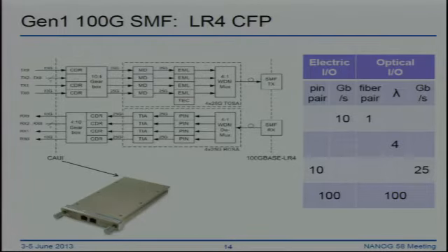By the way, it's about the size of a mobile phone. It had a 10 gig I/O electrical interface, but used 4 25G wavelengths. So again, the WDM complexity is actually making the interface simpler for you as an operator because you're only dealing with a duplex LC connector.